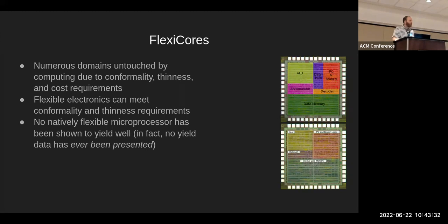We've just prototyped some LP ROMs, so laser programmable ROMs. These are ROMs which you build as a typical ROM, but then after they've been manufactured, you go over with a laser and you remove some wiring, and now you have a programmable ROM. So these are a write-once ROM that you can use to write your program into.